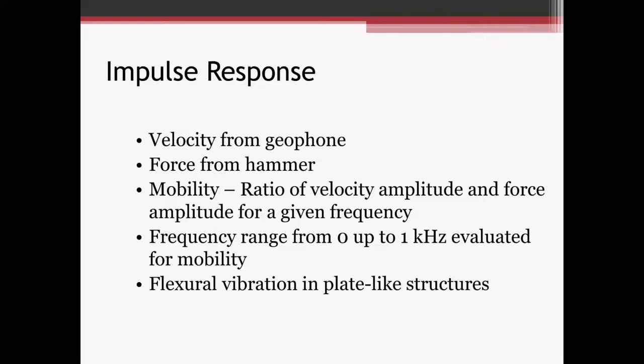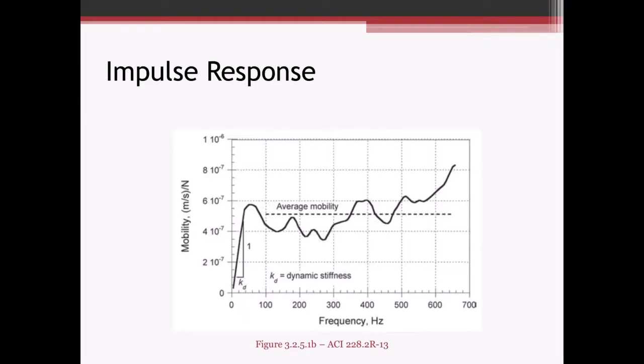If there are voids below the slab, those typically show up really well. We're plotting the mobility over a very low frequency range. And as I mentioned, it can be really good, mostly for plate-like structures. Again, it's this flexural vibration. If you can picture what's happening, it's that flexural vibration.